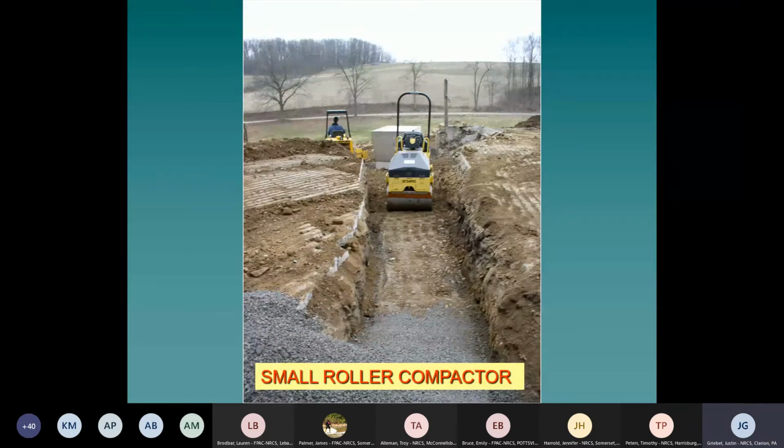And here we're roller compacting the ground in. We're going to have a concrete slab over top of this. We don't want any settling going on. And we're up out of the deep trench, so we can have a manually operated compactor there. It's a smooth wheel roller.